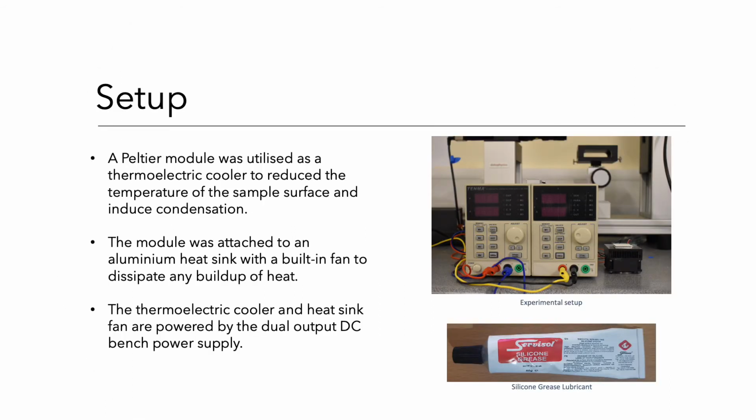In experiment 2, a Peltier module was used as a thermoelectric cooler in order to investigate the failure of hydrophobic surfaces during condensation. The module was attached to an aluminum heatsink in order to eliminate any buildup of heat. The system was powered by a dual-output direct current bench supply. Each tested surface was placed on the cooler and recorded for a duration of 3 minutes.